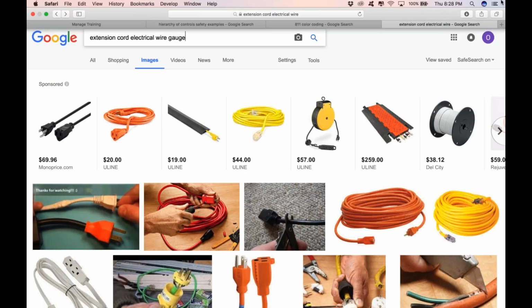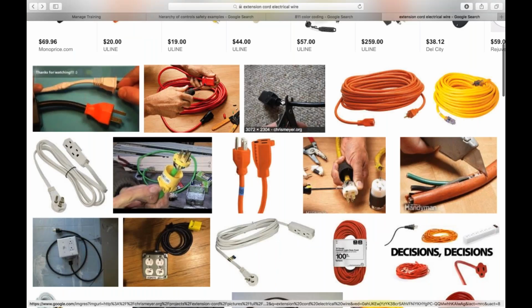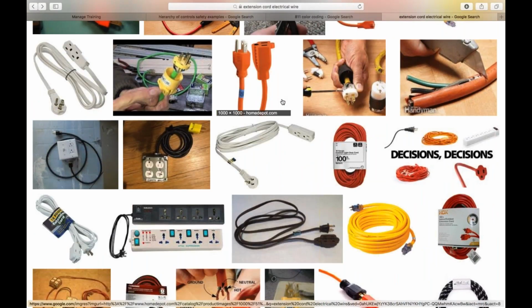Do we need any hot work permits, cold or safe work permits, vessel entries or confined spaces? Do we have non-permit required confined spaces? Do we have permit required confined spaces? We have to identify the confined spaces, period. We're going to have to know what's a confined space, and then identify what is a permit required confined space for certain. Any gas testing, we're going to have permits for that as well.